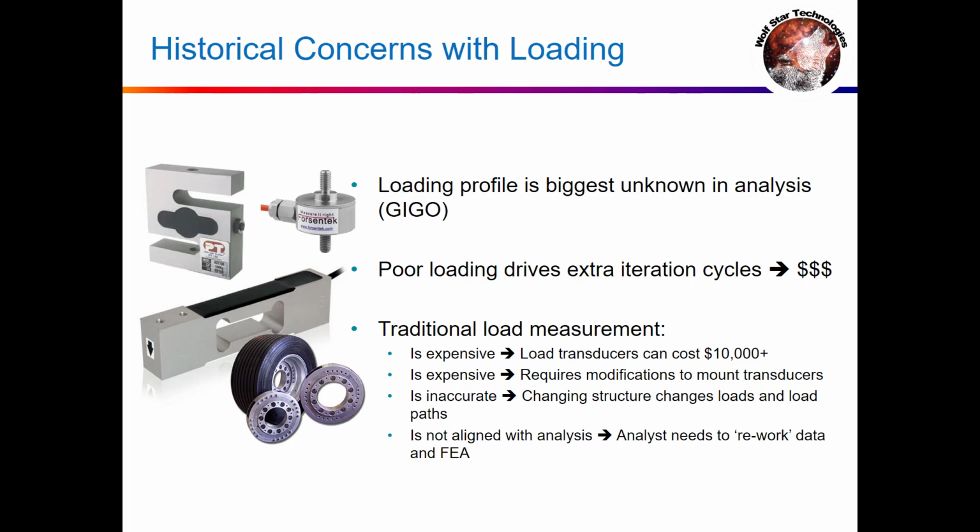In the US, we've got this term called GIGO, garbage in, garbage out. So if you're just guessing at the load cases, you're guessing at the results. So you're going to go through many iteration cycles because you don't fully understand the loading, and you're going to go through the analyze, design, build, test cycles several times.